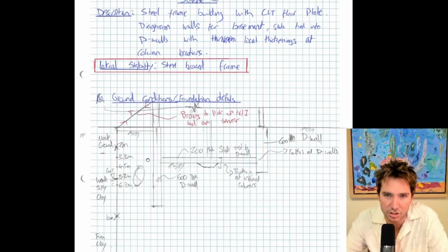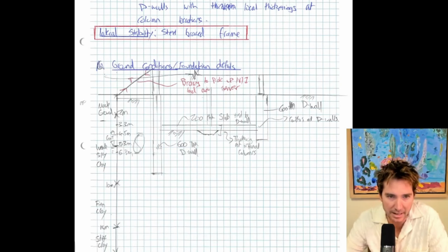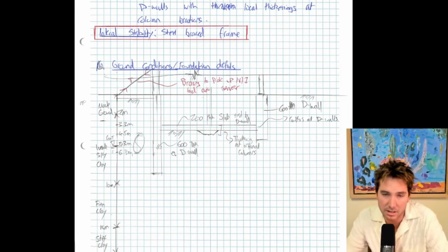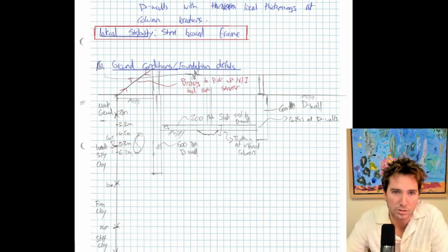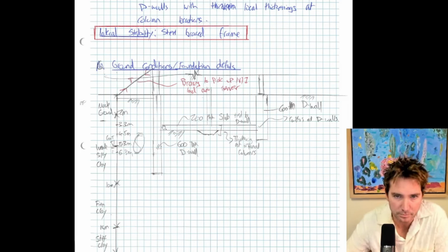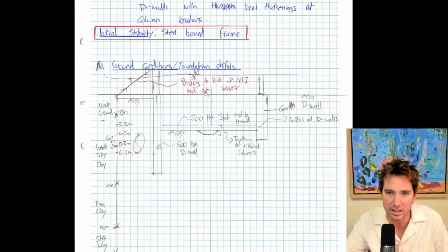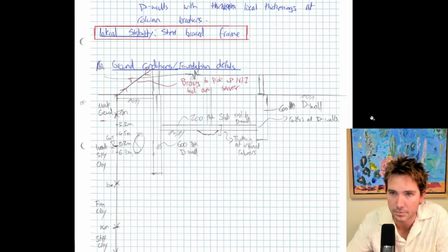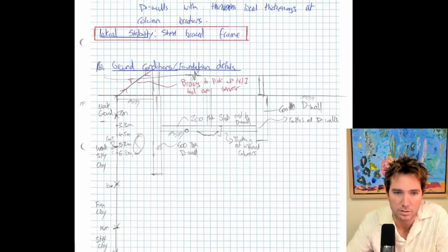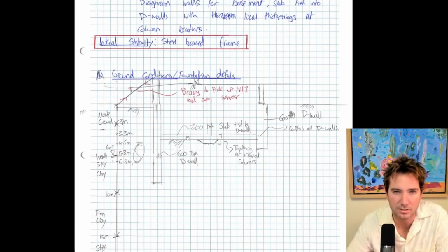So here, the ground conditions, I'm showing it again. This time, instead of using secant pile walls, I'm using 600 thick diaphragm walls, where the slab is a bit thinner because it's actually tied into the D walls in this example. So I get the benefits of continuity there, but I'm also adding some thickenings at column locations. You'll see I've got different grid spacings and different column spacings in this scheme. Little note here saying couplers at D walls.